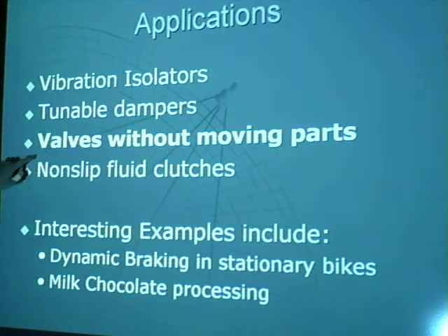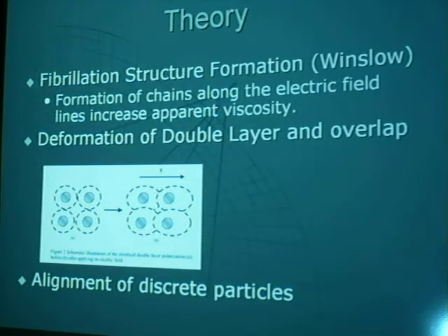The principle of that fluid acting like a solid can be applied to a valve without moving parts. Other applications include vibration isolators, tunable dampeners, non-slip fluid clutches, dynamic braking for stationary bikes and other exercise equipment, and milk chocolate processing. Molten milk chocolate itself is an electrorheological fluid, and that can be used in its processing.